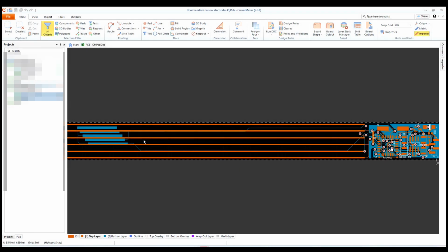The board has been designed in Altium CircuitMaker and contains one mutual capacitive sensor for the lock button. We have 5 interleaved electrodes, 2X and 3Y. The unlock button covers the entire free surface of the board's backside. Here we have made 6 interleaved electrodes, 3X and 3Y. These are made thin to reduce the default capacitance. And now, let's fire up CapExt and build our virtual prototype.